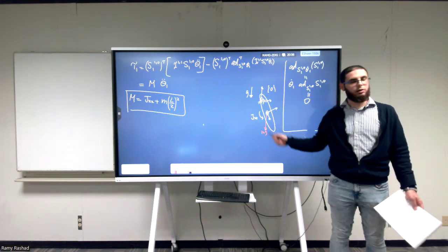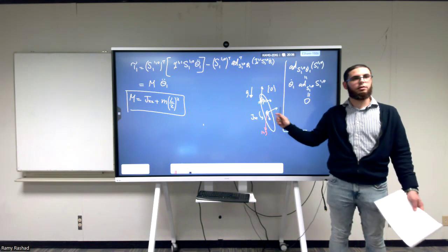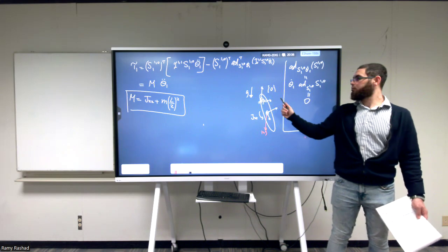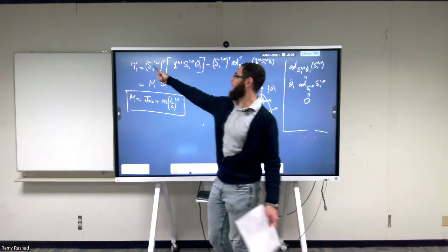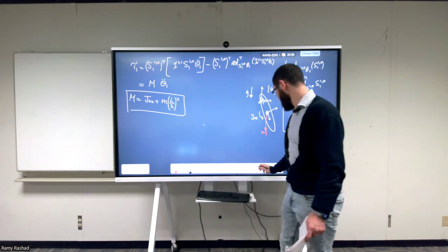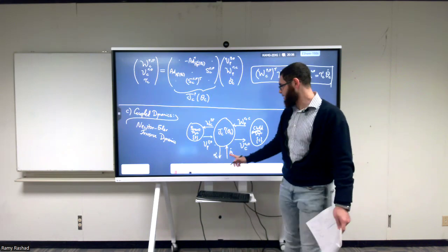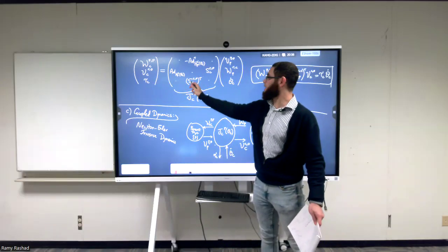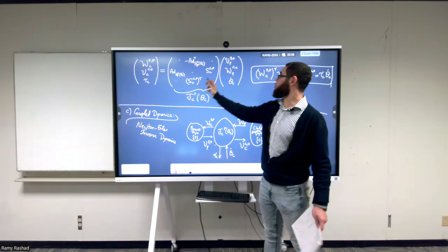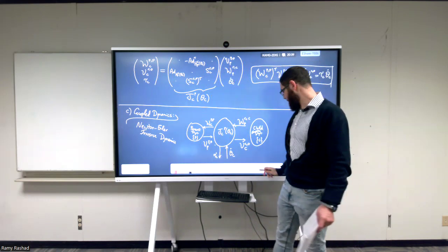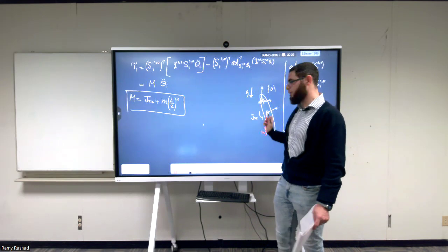I can work out what it looks like, and then I transform it back into a torque by multiplying it by the S, right? You remember what we said in this picture: the torque is equal to the S transpose multiplied by any wrench here. So if I put here the wrench due to gravity, it should be equal to that red one.